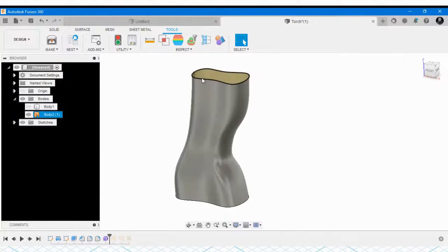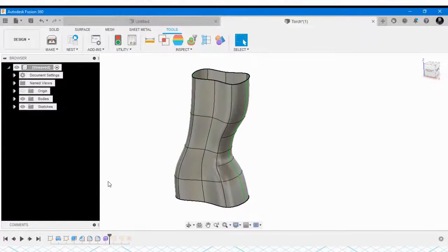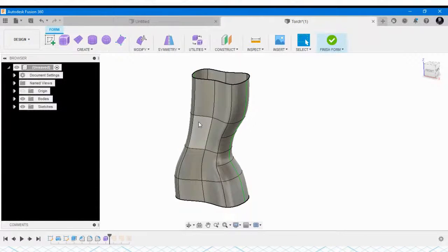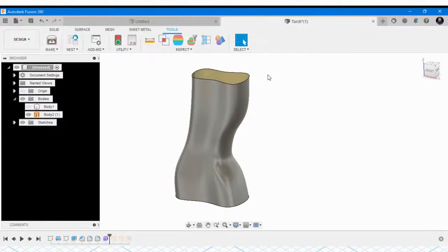But if you save it as an f3d file, you can edit it also after. Let's say that I want to edit this form. I right-click in the timeline and select edit, so I can edit it now. But if you don't come out of the form and don't save it, it will be a messy thing.